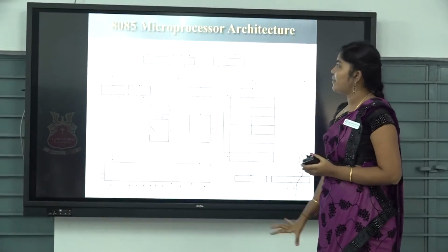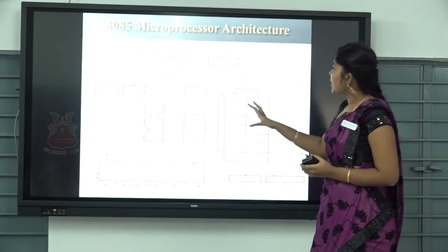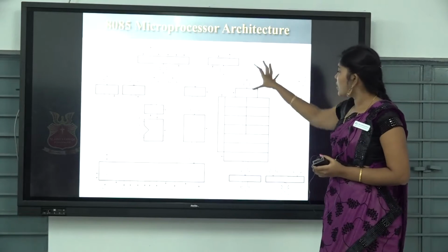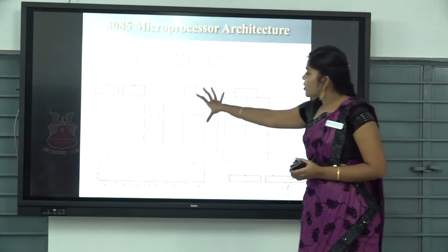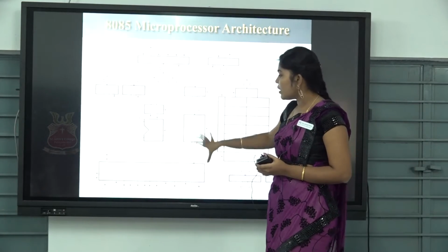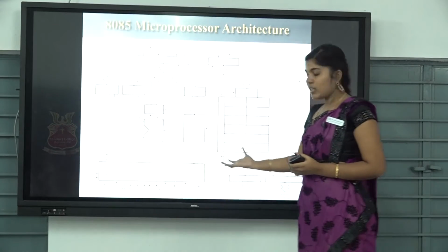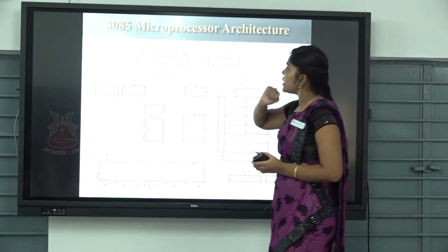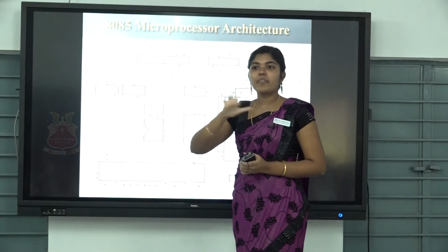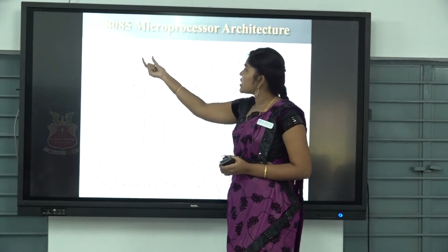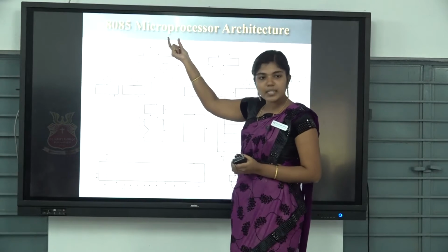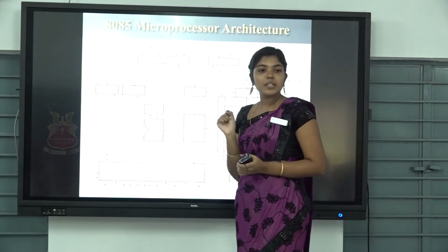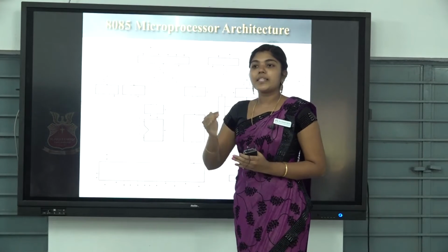So this is the 8085 microprocessor architecture. Here the functional blocks are ALU, interrupts, serial I/O control, set of register arrays, instruction register and instruction decoder, control and timing signals, and the address and data bus interfacing units. First we see that the 8085 microprocessor has 5 interrupt signals: INTR, RST 5.5, RST 6.5, RST 7.5 and TRAP. These interrupt signals are used to interrupt the executing program.